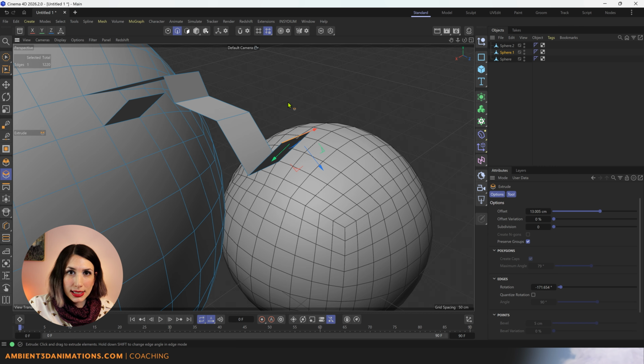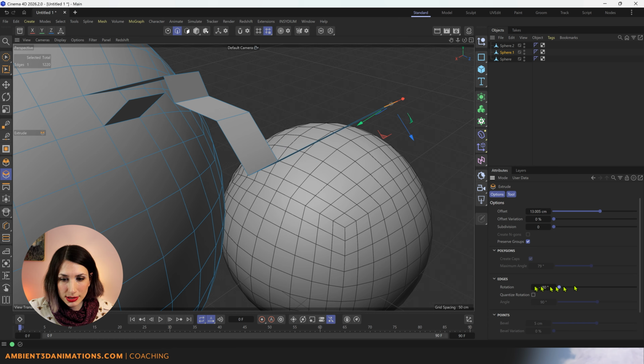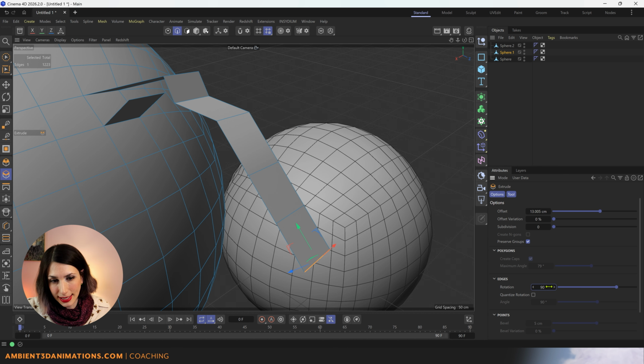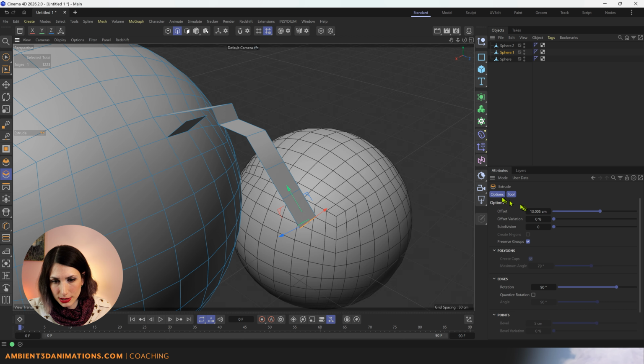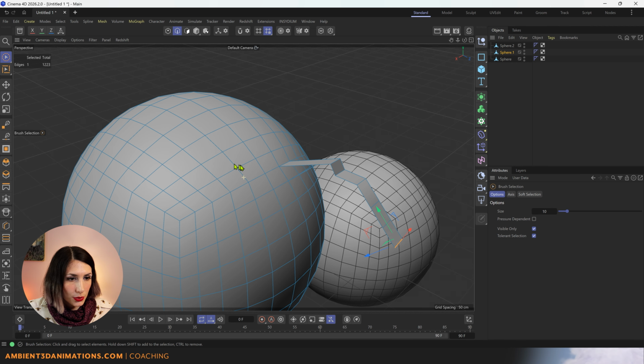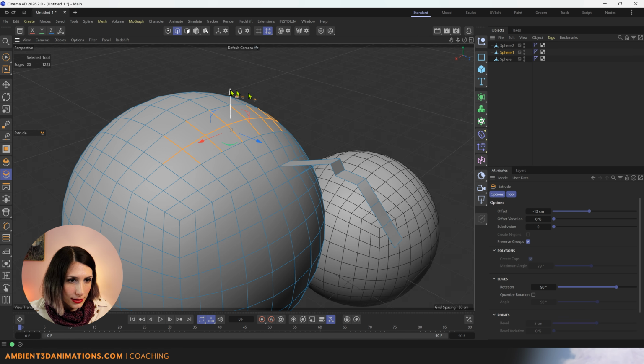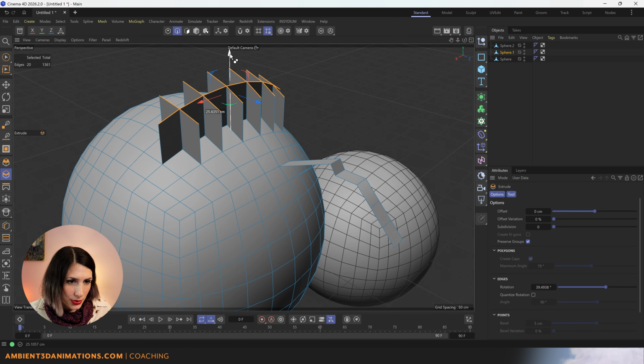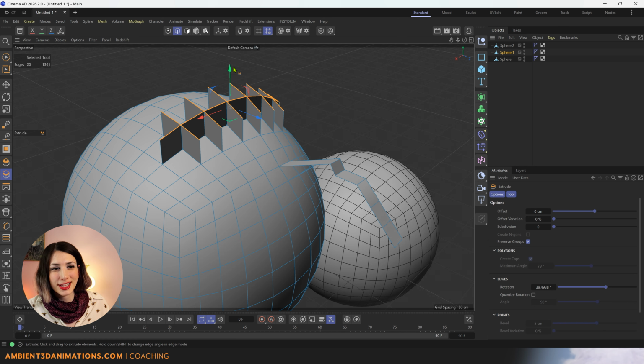So you can use those hotkeys, shift and clicking and dragging in order to rotate this, or you can just adjust the value in here manually and type in something like that. So you have those controls for your edges. And by the way, these options up here also apply to the edges. If you are extruding multiple edges here, maybe I'll actually hold Control and then move these up. So that's another way of extruding, is you can hold Control and use this up arrow.